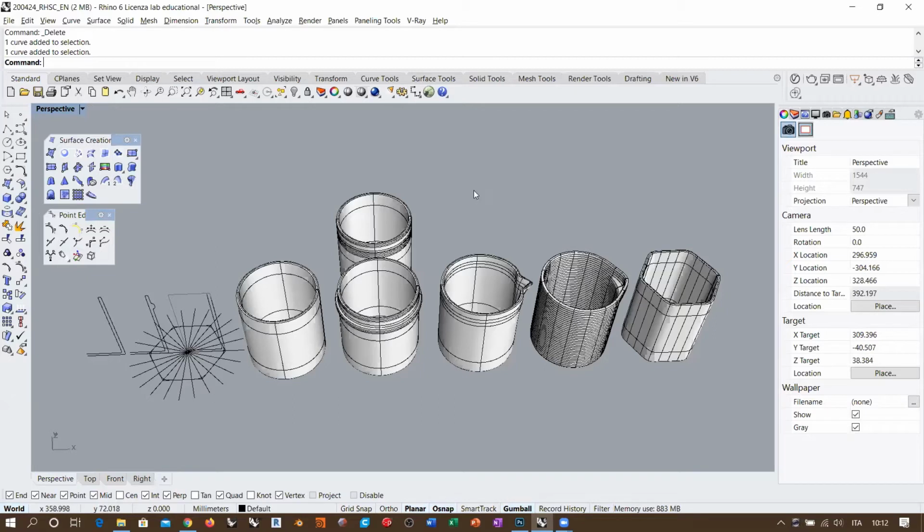When you talk about subdivision surfaces, you are normally talking about meshes. And in that case, for example, there is always this transition between the SubD object and the mesh object and so on. And when you switch to a NURBS object, then normally you will have polysurfaces with all the consequences of having polysurfaces instead of one single surface. In terms of continuity, yes, it allows you to create very smooth sets of surfaces or very smooth meshes, actually.